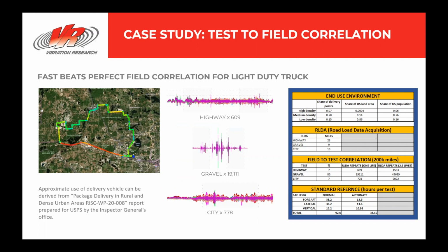This was then processed using Vibration Research's fatigue damage spectrum to arrive at the target lifetime damage value for this particular application. The fatigue damage spectrum process was then applied to generate an accelerated PSD test profile scaled with the shock response spectrum iteration process to achieve an optimal test duration and amplitude for a test that we have confidence will yield only true failures. We then compared the results to the SAE J2380 standard as shown next.